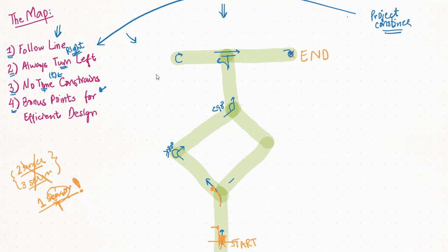In case of a line, it would turn to its left, and it would be continuously detecting whether there is a line or not. When it reaches here, where there is no line, it would start turning right. So this would make it come here. Now here, when it detects the line, it would start turning to its left. So it would be moving in a zigzag direction like this.